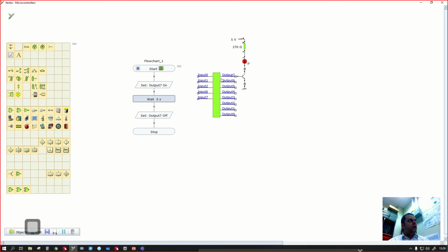Got a transducer driver in there. The transducer driver is receiving from the microcontroller. That's what allows that LED to come on. We could have in that LED and resistor. We could have a motor, a solenoid, a bulb, whatever. All sorts of stuff.